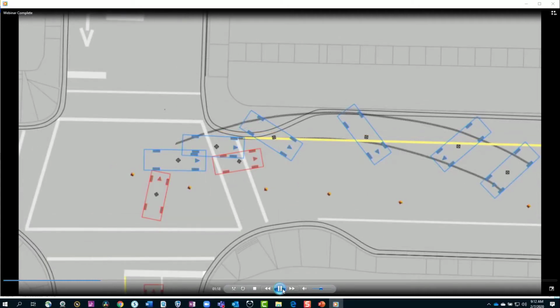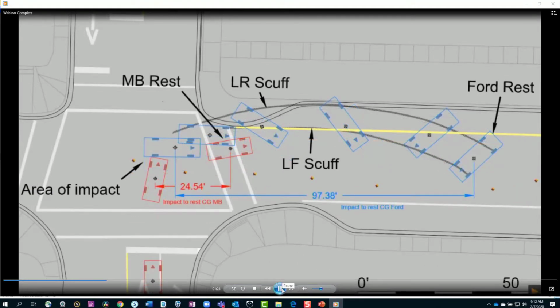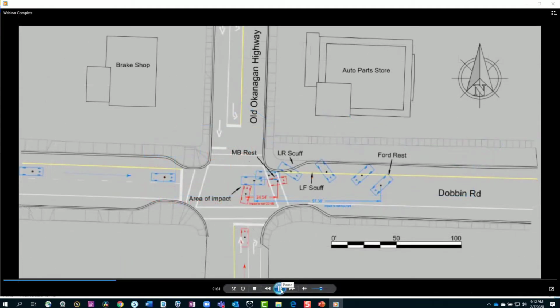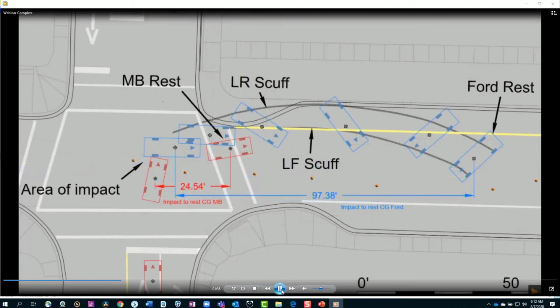And once I've got that done, then I'm going to go to the 2D vehicle spec database and I'm going to add our correct to-scale models right on their marks so that we're actually dealing with the marks on the road that some people might call evidence. Then I'm going to come in here and do the annotations, scuff marks. I even took the measurement tool and did a center of gravity or CG measurement from impact to rest.